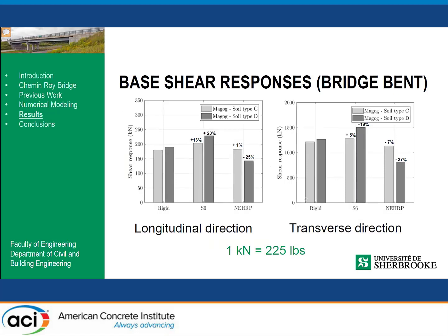In this case, you have the shear response at the base of the bridge bent in the longitudinal and transverse direction. Again, the results here are in kilonewtons, but I gave you an idea of what it means in pounds. So like I said, the natural periods are typically short for this type of bridge due to its relatively high stiffness.